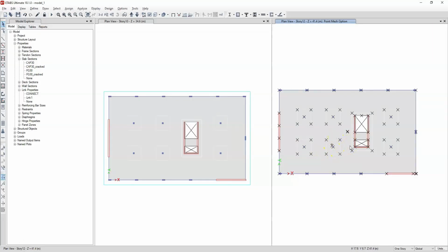We observe that the point is also not at the geometric center of the structure, but it is shifted toward where we have more walls and greater stiffness. And on the other hand, we clearly see that there is a plane asymmetry in this geometry.